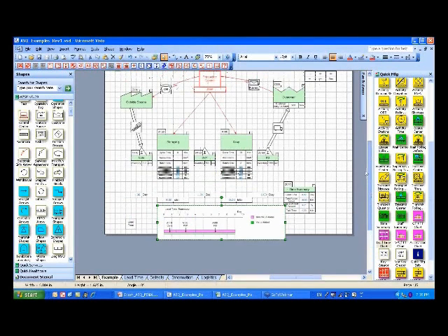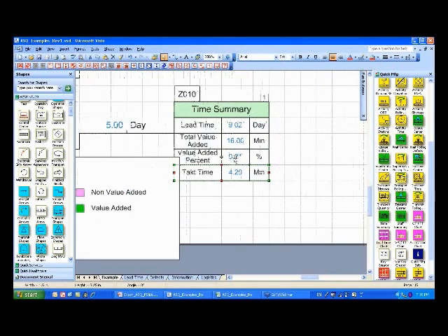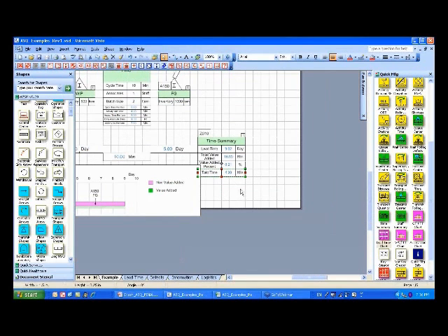If I was to look at the idea of capacity, can I actually meet this customer demand? Remember I said that takt time, here the takt time is calculated as 4.2 minutes. Takt time is completely a function of my available time and my customer demand. It says nothing about can the factory actually produce that, because it's calculated as the available time divided by that customer demand. So right now it's saying if I had steady state production throughout the full 14 hours of that day, then I would want to produce a part every 4.2 minutes, a good part every 4.2 minutes.